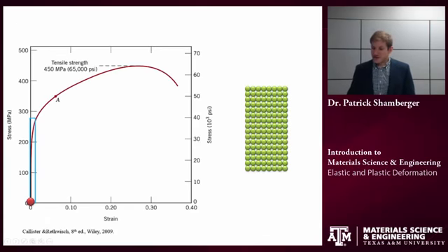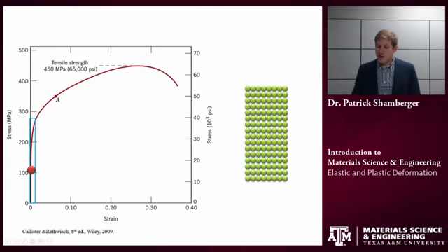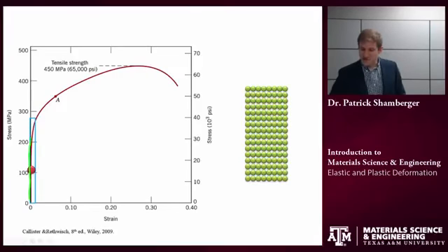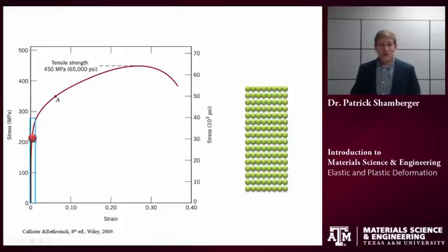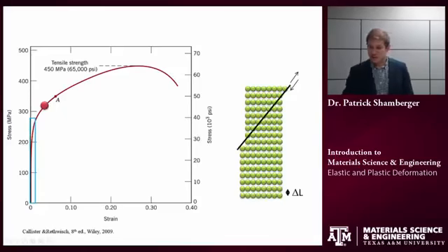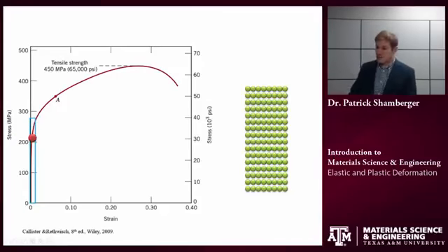Okay, so what happens? Again, initially, a sample undergoes elastic deformation in this relatively small elastic portion of the curve. But as soon as we go past that yield stress, so in this case, the yield stress is somewhere right around here, we start to see an irreversible deformation. So in the case that we're looking at here, this is something that you would see in a metal, for example. And so that permanent deformation is caused, in this case, by slipping along atomic planes.